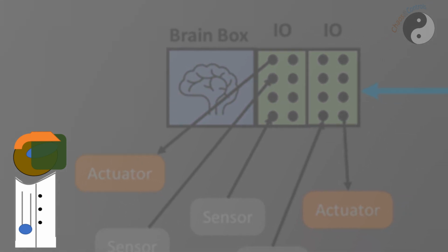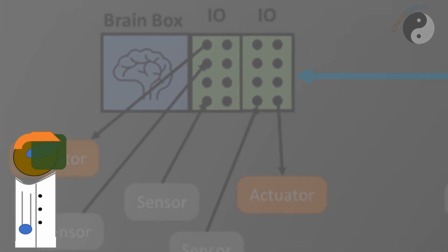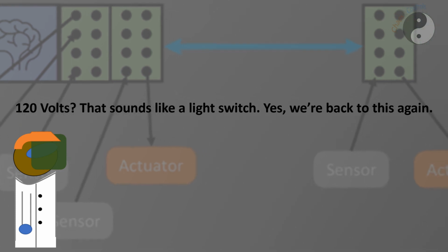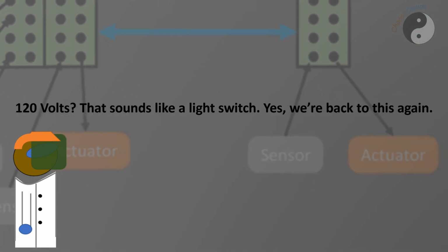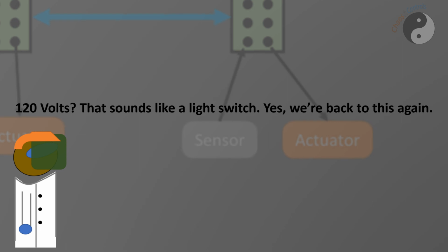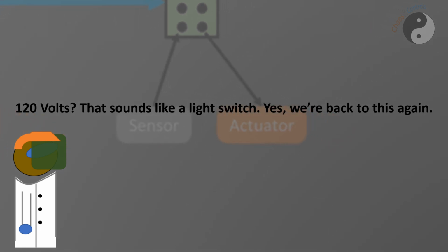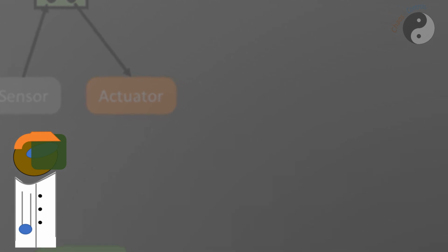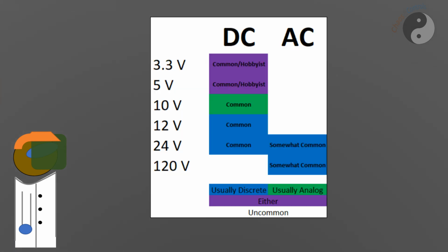And so if I have a 120 volt signal, that is an on, and a 0 volt is off. Subsequently, usually when you see a 24 volt system, it can be a DC system or an AC system. I suppose technically that would be the case on the 120 side as well, but you almost exclusively, at least stateside, see 120 volts AC. So we can have AC and DC, we can have 24 volts and 120 volts.